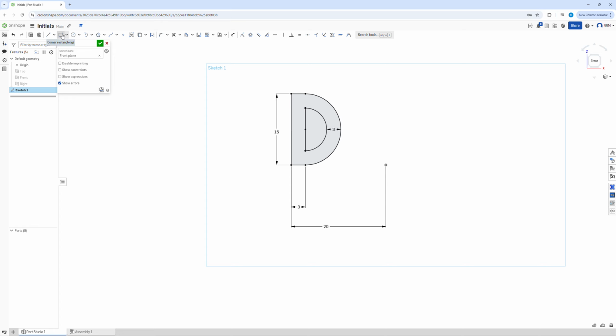We can now move on to the T. Let's do something slightly different. Let's go for a rectangle. Let's bring a rectangle up here and let's put a rectangle up here. Now we could connect these two together, so I could click on this one and I could make them perhaps coincident. Now those two are joined there. And I could potentially get rid of this middle part because it's a bit messy, so I could use the trim tool. Or I could use the construction line tool here, like so, make that a construction line,